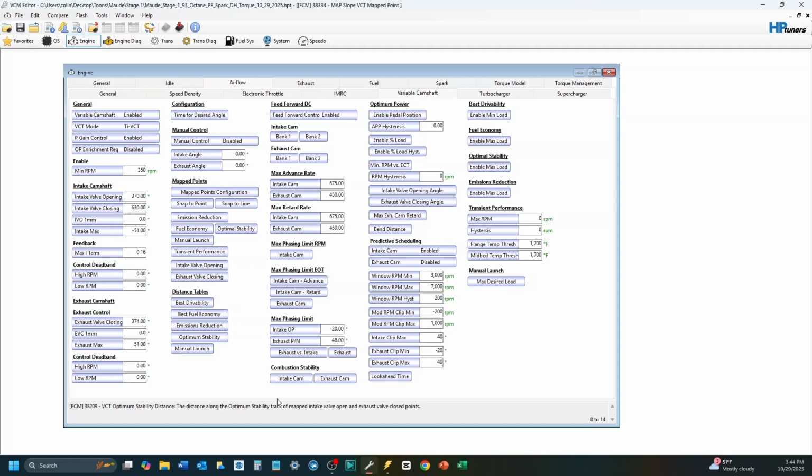So tables 0 through 20, which is both the high and the low state. Then we're going to have a third video on power, where we'll look at how we calibrate the wide open throttle power tables. And then with all that in hand, you have a complete speed density tune.